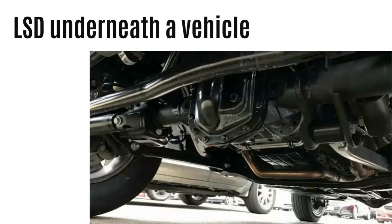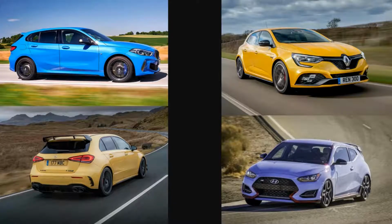Mechanical differentials are expensive to develop and fit, which is why we'll often only find them on more expensive vehicles and hot hatchback versions of compact family cars. However, with the advance of in-car electronics, some manufacturers now offer e-differentials, which do a similar job to an LSD by using wheel speed sensors that tell the car electronics to apply the brakes to a spinning wheel in an effort to control a car's power delivery.